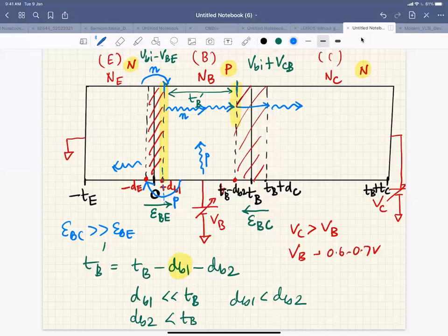If you look at this junction here also, I have excess holes at this point minus DE, then there is a concentration gradient and the holes will diffuse, and they will recombine, as I told you during the PN junction also, because here I am taking the contact, and at the surface all the excess holes will be recombined, right? So they diffuse, there is a possibility of recombination, the holes will recombine also in the emitter region, and the rest of the holes will recombine at the surface.